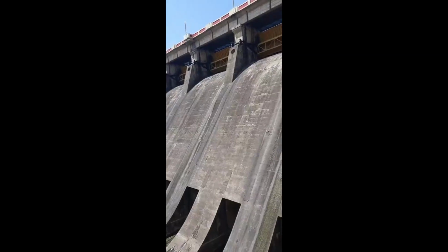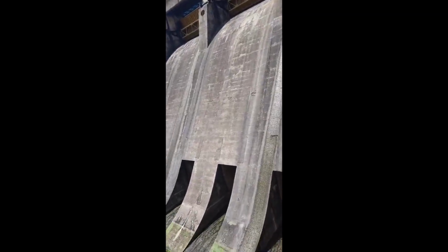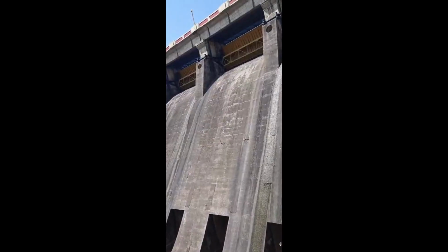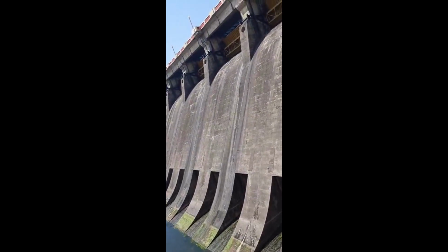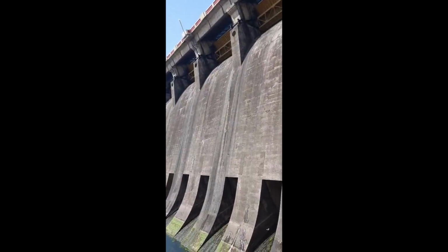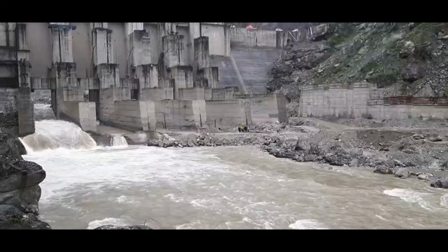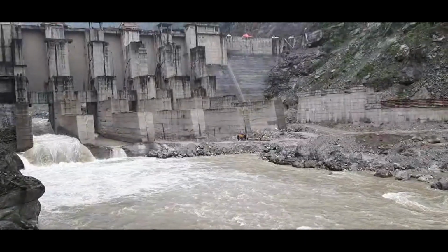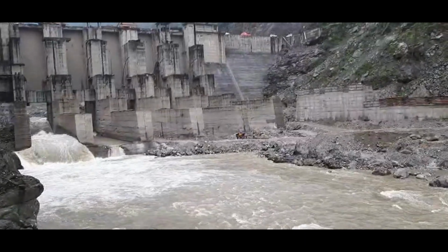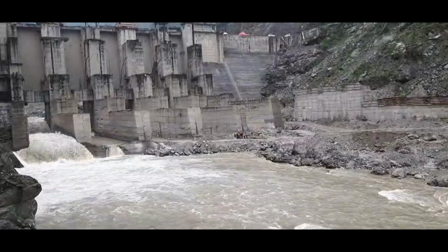We can see here the combination of two different types of spillway. The top is Ogee Spillway and at the bottom, sluice type spillway is adopted. With this, discharging capacity and sediment management is solved. We can see Orifice Spillway here. The water is passing through Orifice Spillway. Due to high incoming floods, the spillway adopted is Orifice Spillway here.